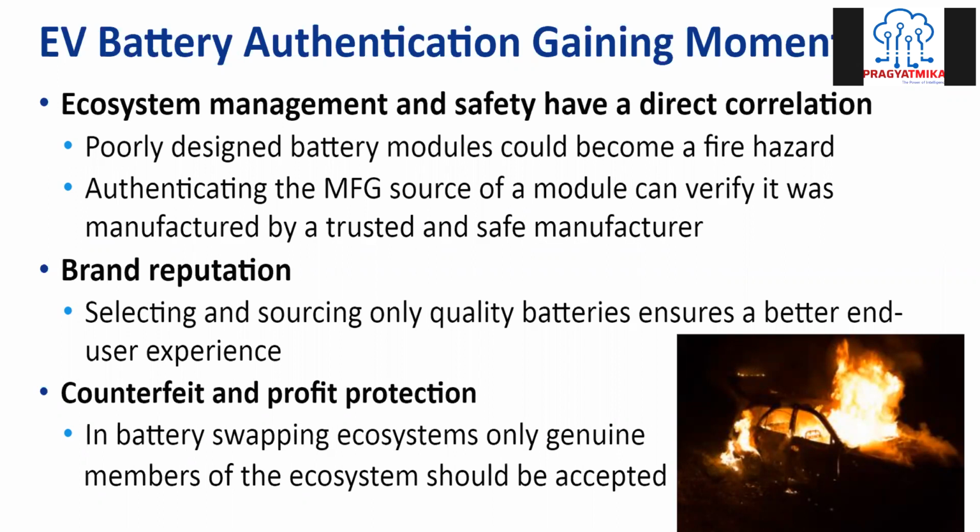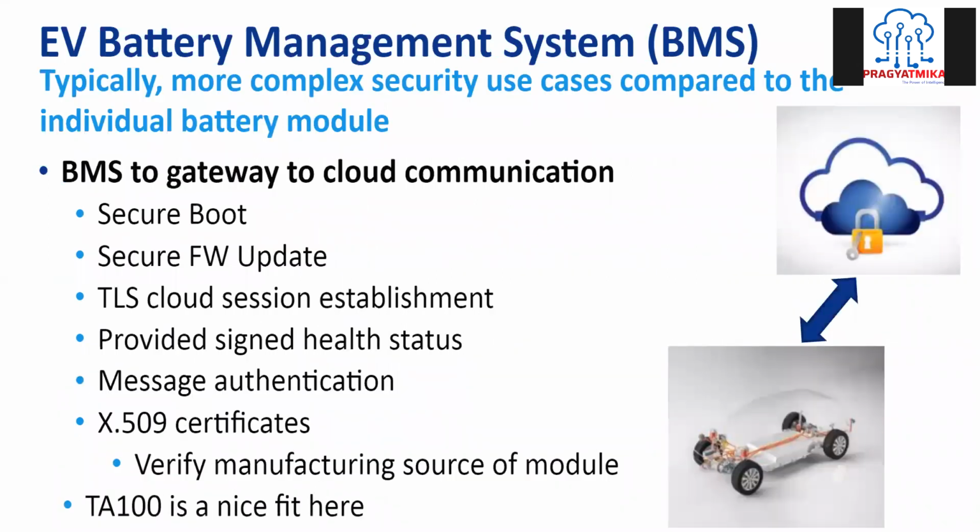So how to prevent such counterfeits and specifically when this swapping ecosystem is going to be implemented? There is an authentication mechanism that we need to implement. That authentication will be either in the BMS or a separate authentication module in your pack. If it is an IoT BMS, it is better to implement the authentication in your BMS itself, where it gives you the secure boot features and the security certifications, and whatever messages are coming through the cloud should be encrypted and certified.